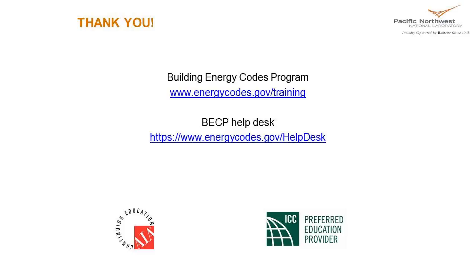There's still fire ratings. So that one provision I showed you on that slide that said don't forget about the other codes, one was the fire code. And you want to make sure that you have a fire rated tested assembly and that you're meeting that, and that's another code provision, and more than likely the building department will want to make sure that you have that. I mean, you want to make sure that you're meeting the fire code for sure, and other things come into play. So yeah, it wouldn't have to deal with the energy code unless it becomes a conditioned area.